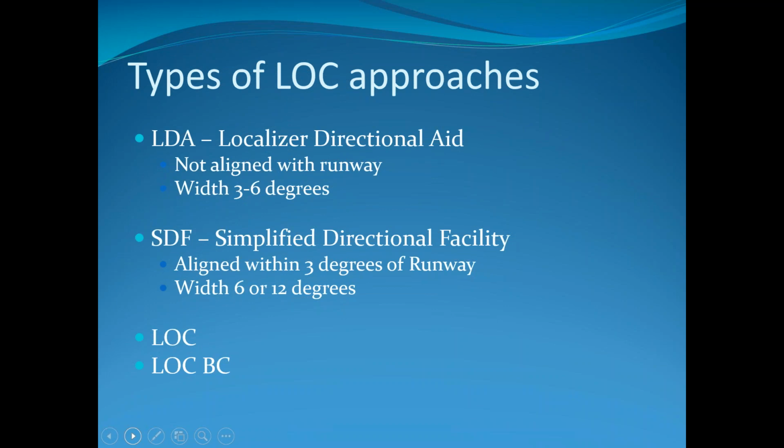here in St. George, because of the mountain that's straight out here, straight off the end of the runway, Pine Valley Mountain specifically, because of the proximity of that mountain to the airport, we can't technically do a straight-in ILS system because that mountain is too close for that angle of the approach to come down over the mountain. It gets too close to the mountain. So in order for them to accommodate that, they had to change their ILS into what's called an LDA.